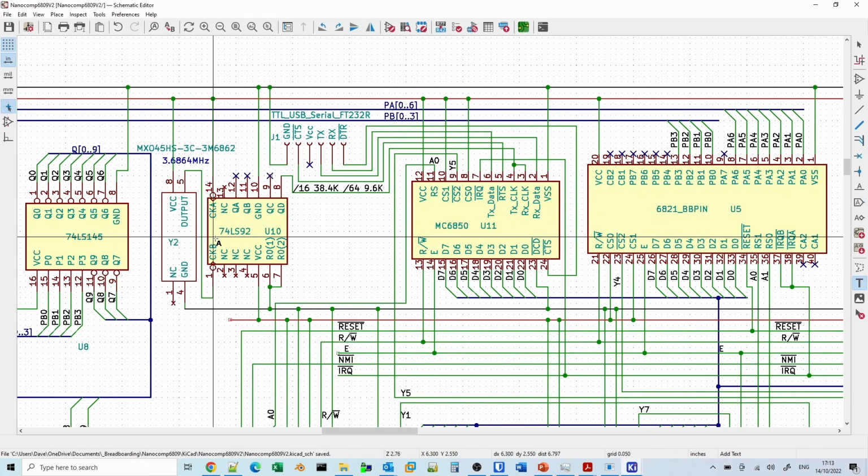out of that. The 74LS92 has 2 clock inputs. Clock A input is to do the divide by 2. So clock A goes in there and comes out of QA, and then we would feed QA into clock B if we want to do divide by 12. But because we want to do divide by 6, we're just going to feed our 3.6 megahertz signal into clock B, and coming out of D will be our divide by 6 signal.